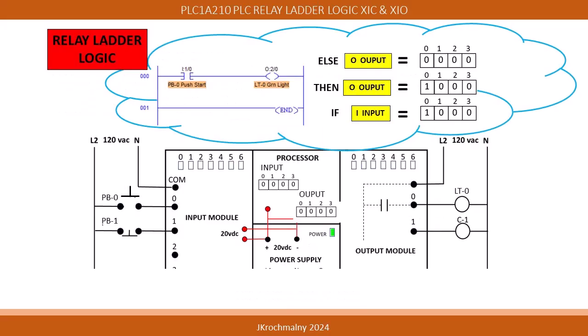As mentioned in earlier Introduction to Programmable Logic Controller presentations, the PLC Central Processing Unit, or processor, stores the operating set of instructions for the assembly. The operating set of instructions are often written in a form that resembles an electrical ladder diagram. Towards the top left of the graphic, we see an example of the relay ladder logic that controls PLC-connected loads based upon the condition of the input field devices.